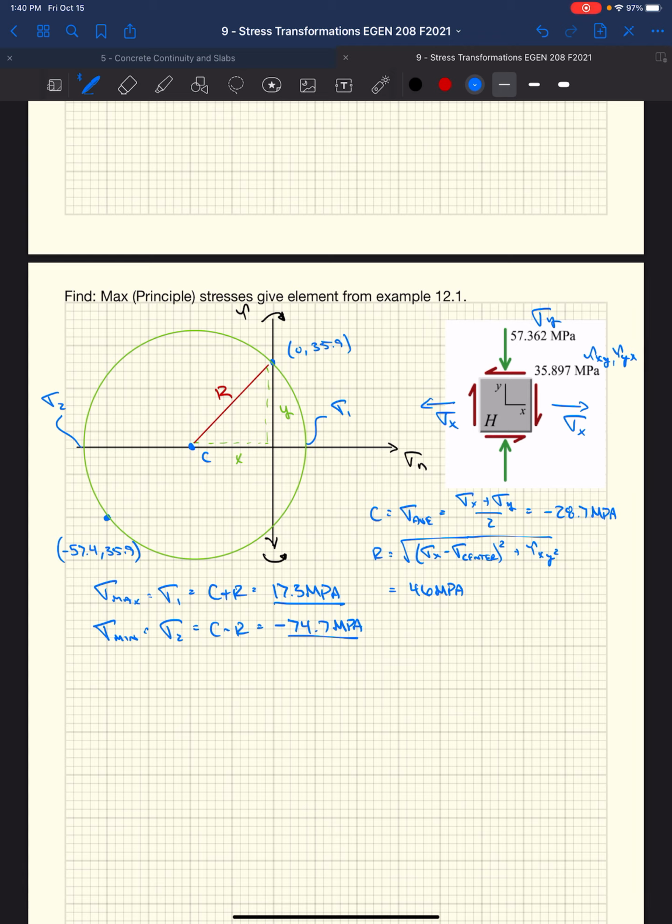we've determined here. Well, maybe this pole is aluminum and it can't handle more than a compressive stress of 50 megapascals. Well, you start back at the beginning, right? Based on this loading, the demands will be as calculated based on the geometric properties of the pole. We would have to change either the loading or the geometric properties, right? We have to make it stronger, making the allowable stress higher. We'd have to make the pole diameter larger so we can increase our polar moment of inertia, right? We have all these moving pieces that would affect ultimately what we calculate as our maximum stresses.